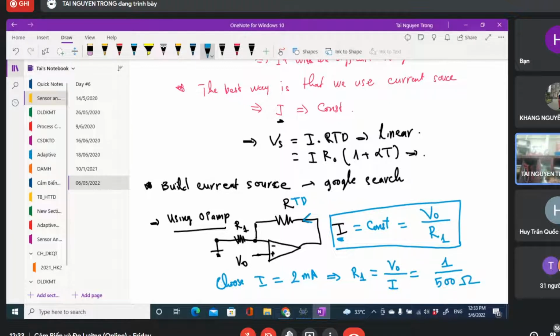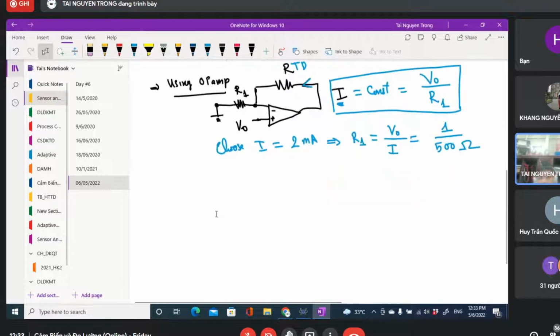At the first step we determine KC, based on the error requirement. Normally we have 3 requirements: one related to the error requirement, one for phase margin and one for gain margin. We will use these 2 requirements to design our controller, and then we check if our designed controller satisfies this requirement.